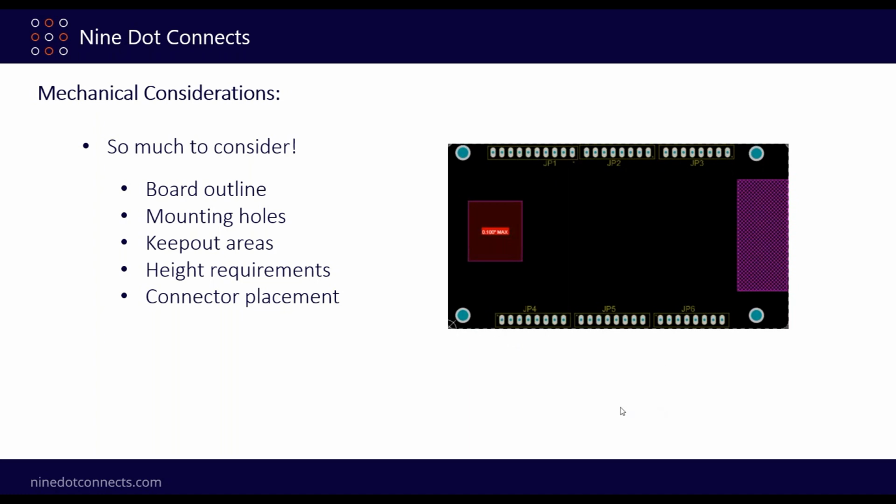So you may get through an entire board layout, you think you've done the right thing, you put it in the exact position your mechanical engineer wants it in, and you hand it over to him. When you're all done, you hand him the step file, and he or she comes back and says, hey, these connectors aren't even close, right? Now you're ripping up that board, you're getting out that jackhammer, and it's going to feel like that, right? You're going to rip everything up, and it's going to take a lot of time. So early decision, making sure everybody understands what's going on is super important.